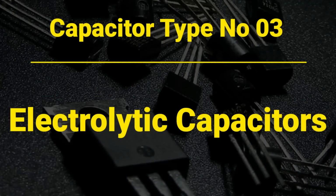Ceramic capacitors are available with a maximum of 100 microfarad capacitance, which is still very low for many power supplies. Actually, we need a higher capacitance. Here is where the next capacitor type comes into play. Capacitor type number 3, electrolytic capacitors. Electrolytic capacitors are used where we need high capacitance. It seems weird, right? Because technically it's possible to make higher capacitance ceramic capacitors. You may ask, why don't manufacturers make high capacitance ceramic capacitors and instead they make electrolytic capacitors?